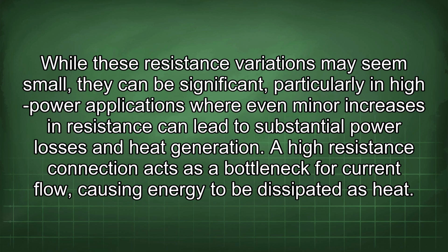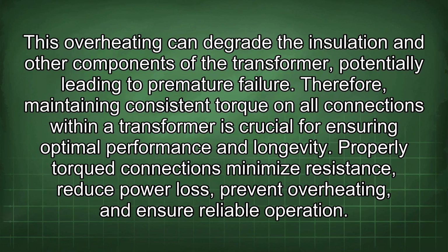A high-resistance connection acts as a bottleneck for current flow, causing energy to be dissipated as heat. This overheating can degrade the insulation and other components of the transformer, potentially leading to premature failure. Therefore, maintaining consistent torque on all connections within a transformer is crucial for ensuring optimal performance and longevity. Properly torqued connections minimize resistance, reduce power loss, prevent overheating, and ensure reliable operation.